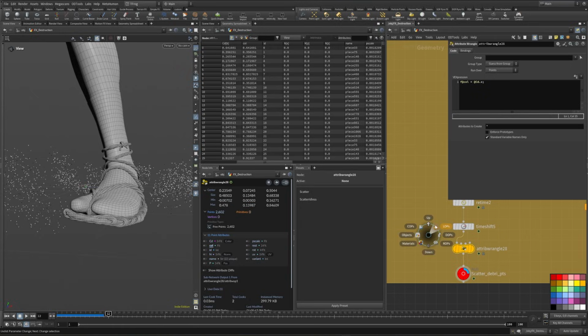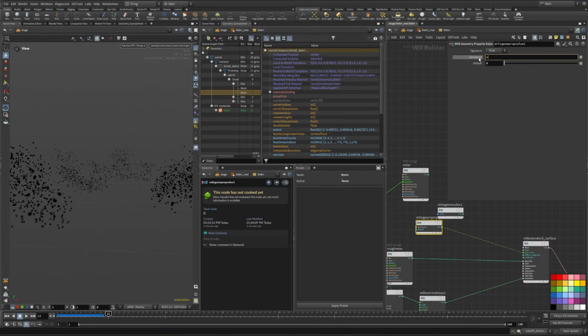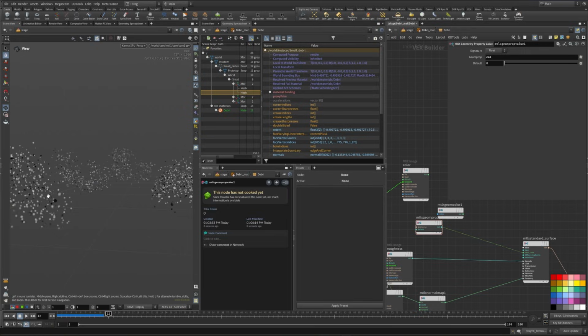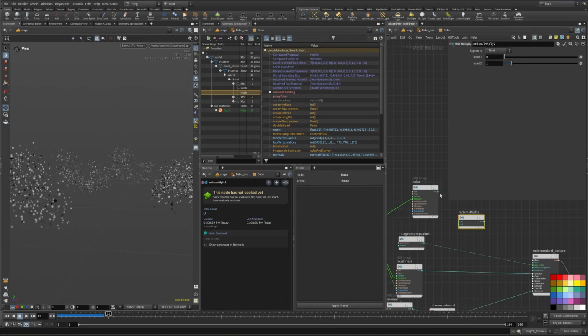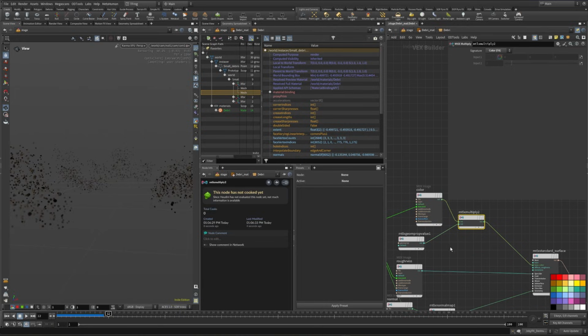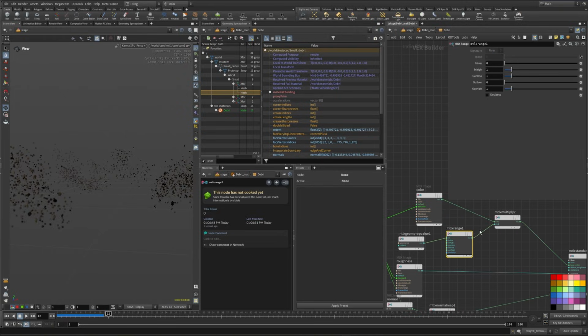We can move back to lops, and I use my color attribute in here. Now I can see all the different colors here, and we can use it as a multiplier for our color attribute. So we're using a multiplier in here. Let's plug this in here and the float value inside here. Plug this into my base color. And we got some darker debris and also some brighter. And we can use a fit range in here also, X range. And let's use the lower value as a 0.4 maybe, or 0.3. And I think this is enough here.